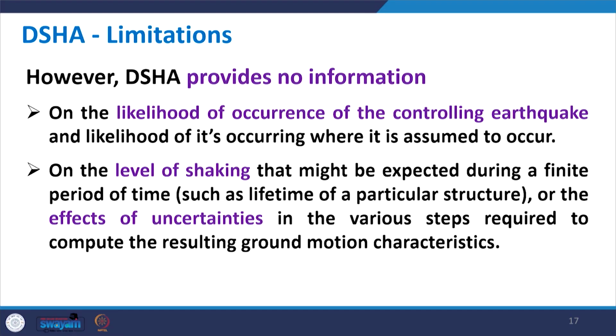Then the second, DSHA also does not provide information on the level of shaking that might be expected during a finite period of time. When we say finite period of time, it is normally considered to be the lifetime of a structure. For example, major structures like dams and bridges have their lifetime, they are designed maybe for 50 years or 100 years. So, normally the lifetime of a structure is considered to be maximum 100 years or so. Whether during this 100-year period that level of shaking will occur or not, that is also one of the issues,